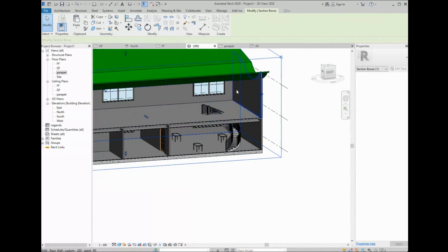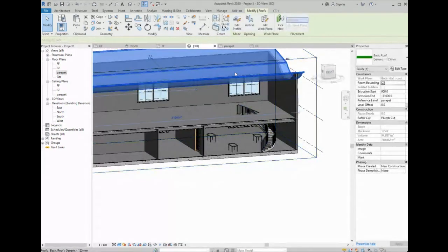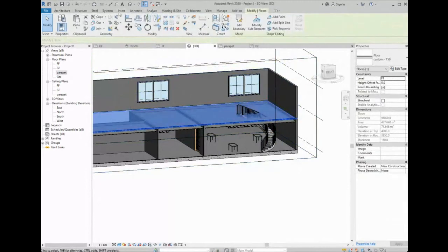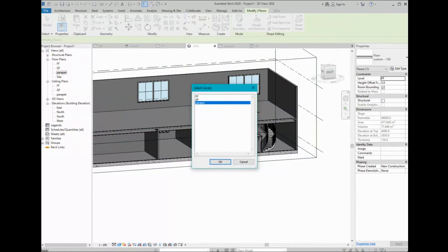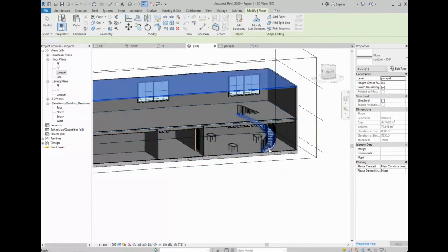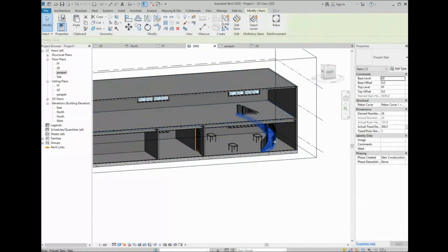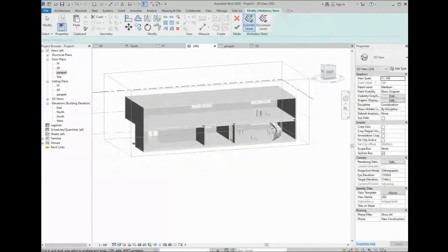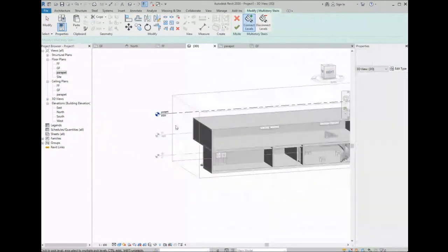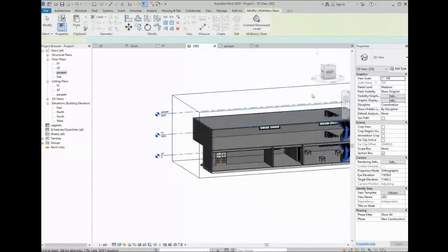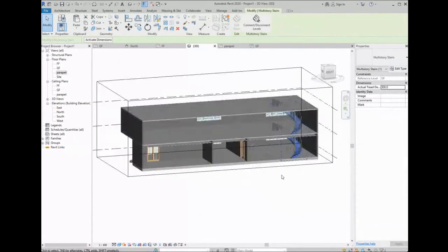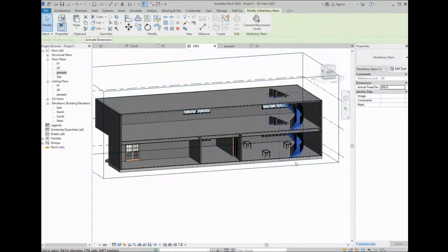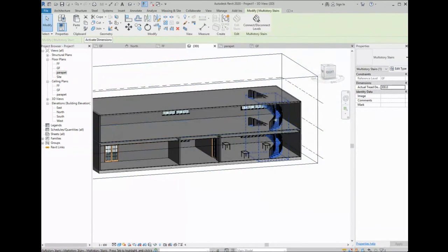If you want to add the stairs to another level that you have, let me just delete the roof for now and copy this one. The flooring, align to parapet, and click on OK. Okay, what you can do is after you're done, you can select this, select level if you want to copy it, select the level that you want to copy it to. So I will select this one. Click on OK, and you will see that it will be copied upstairs.